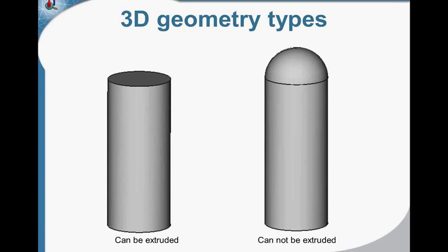So what is the difference? Extrusion means you raise some planar shapes to some predefined distance. And the extrusion model combines the planar shapes and walls. And the angle between the plane and wall is always 90 degrees. It is not always good because in the majority of electric applications, the surfaces are smooth and transitions are not 90 degrees. It has a physical reason because an angle causes an increase of the field stress and electrical insulation may break down,